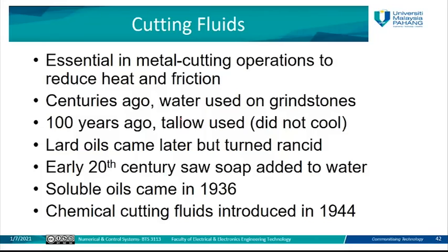Maybe if this drill would normally be used for 10 years, for example, without coolant it might finish within 2 years. Because of this high temperature, which will affect the hardness and the strength of the material or of the tools, they use liquids like fluids. The fluids used are like oil, lubricating oil, and so on for coolant, with some chemical materials, soluble oils, for example. All these types of coolant were used historically in the CNC or NC machine.